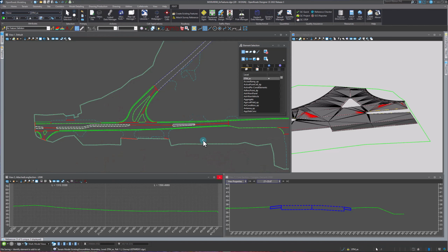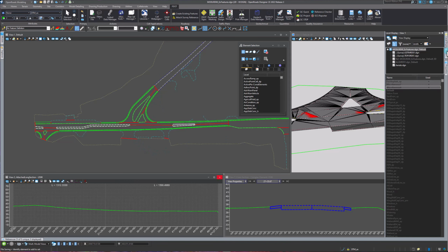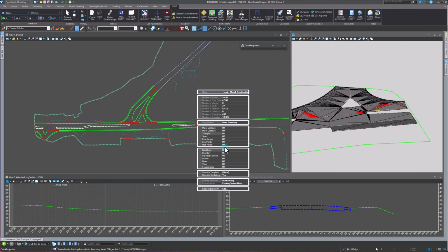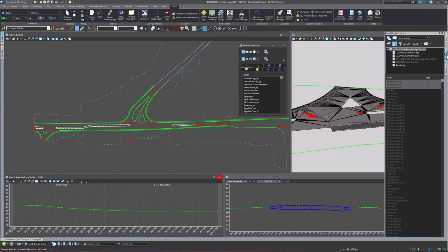And then something funny is happening, I think, because of this create existing features tool. I haven't quite been able to figure out exactly what it's doing. I think it's applying some sort of level filter to turn things on and off, but it seems to be messing with the way that this terrain model is getting shown. So if I come in here, again, I've got it on, override symbologies, yes. If I go to the GDTM, I've got all this stuff is off. So let's turn all this on, set it to default, but that's not doing it either.